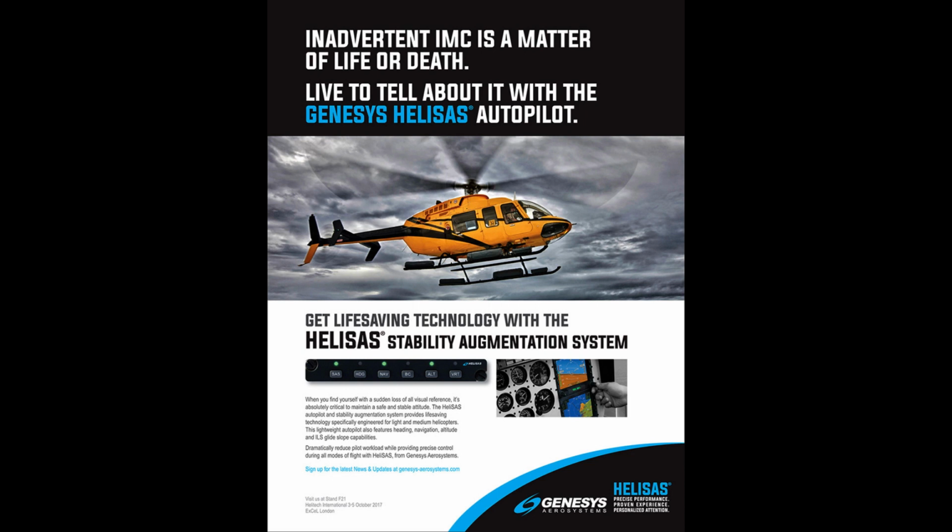This is referred to as a coupled system. An additional component, called a flight director, FD, may also be installed. The FD provides visual guidance cues to the pilot to fly selected lateral and vertical modes of operation. The most advanced autopilots can fly an instrument approach to a hover without any additional pilot input once the initial functions have been selected.